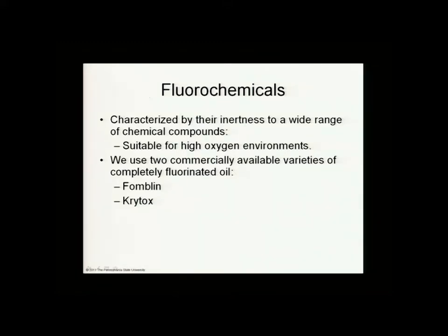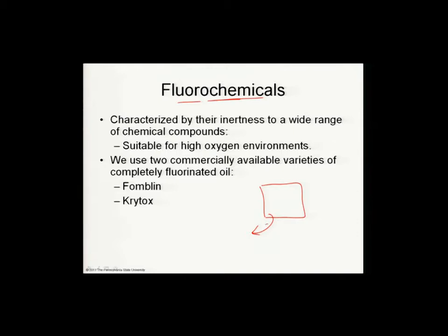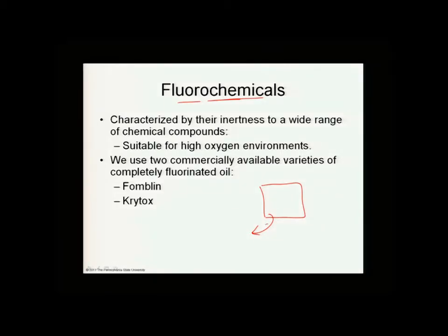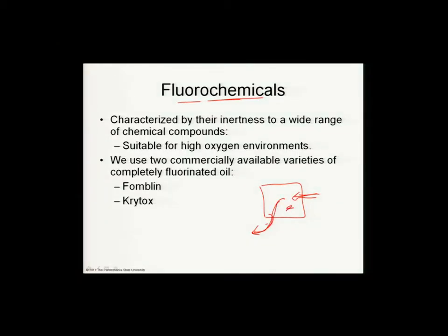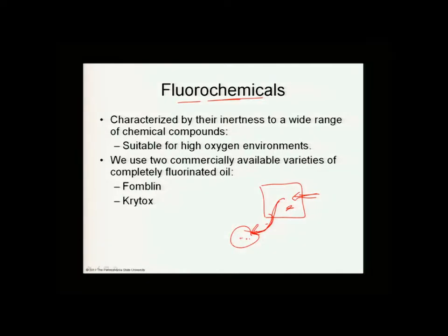So these kinds of oils, synthetic oils, may be of need in situations where you're pumping gases out of a vacuum system. Here's your vacuum system. You're pumping these gases, and there may be a situation where whatever is flowing through here, something's coming in, you're doing some processing, this effluent could react with the pump. And so you have to look at the use of synthetic oils in that case. And of course we know the pump needs oil if it's a regular mechanical pump. We talked about the function of the oil in sealing and in friction reduction.